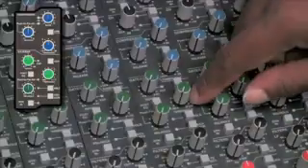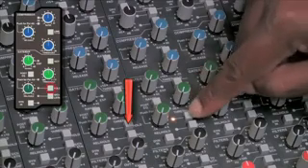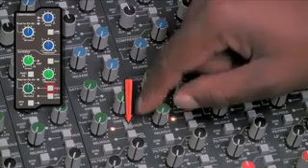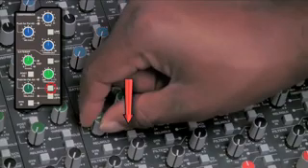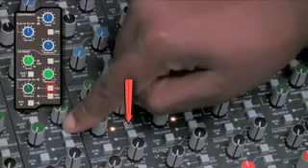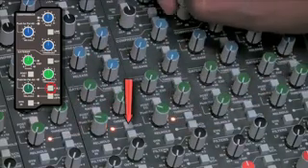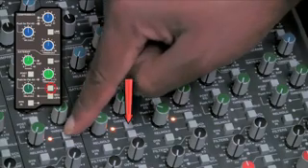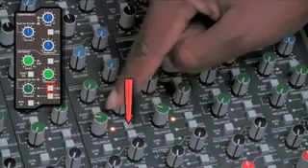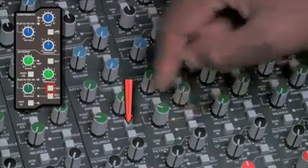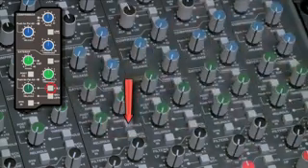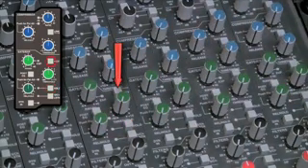Beside the release pot, you have a hold switch. When the hold is active, the release time is set to 150 milliseconds, but the hold time is variable between 0 and 4 seconds by adjusting the release and hold pot. Each channel has a key input. This is used as an alternative trigger source for the dynamics section.